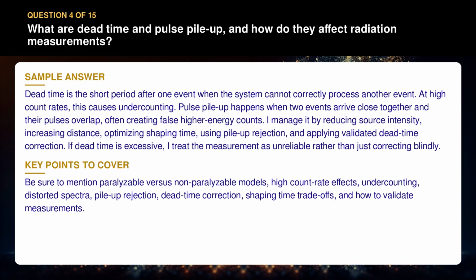Be sure to mention paralyzable versus non-paralyzable models, high count rate effects, undercounting, distorted spectra, pileup rejection, dead time correction, shaping time trade-offs, and how to validate measurements.